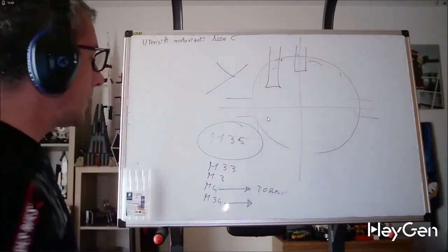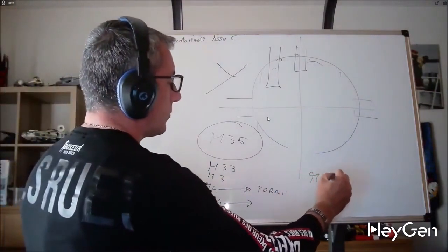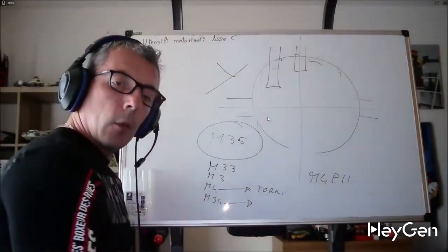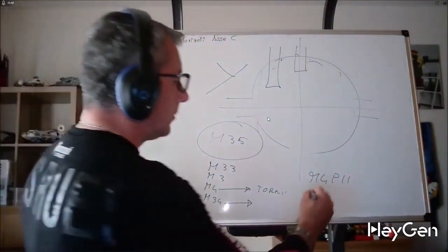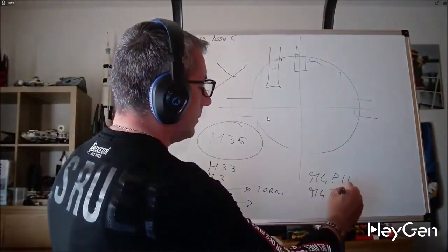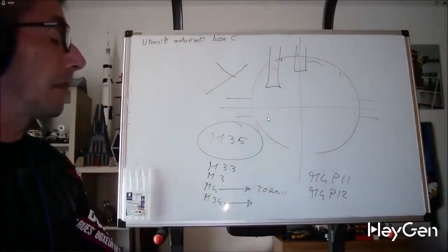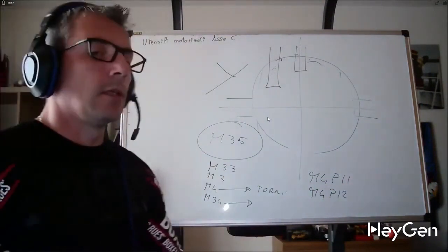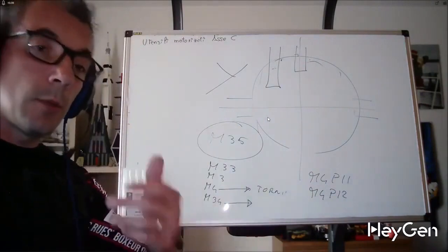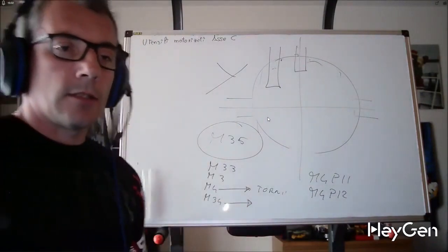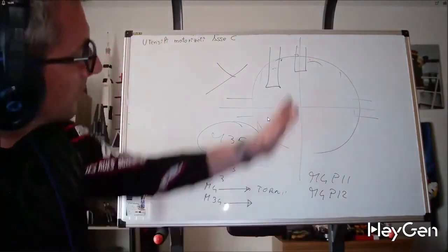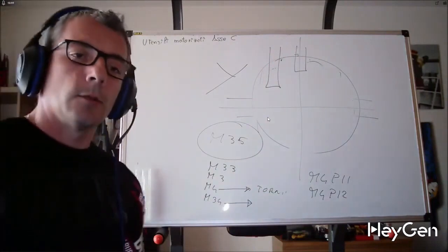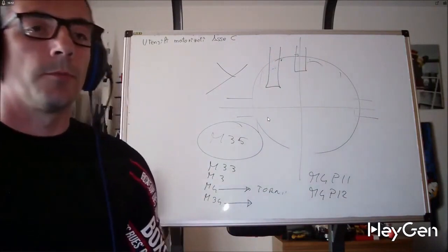On more modern FANUC CNC machines, the command M4P11 is once again utilized to activate the lathe spindle, while the command M4P12 is specifically used to activate the motorized tools. The main difference is that we will use the G112-113 commands to work according to the Cartesian axis, looking at the piece from the front, but I assure you that this is absolutely not a problem.